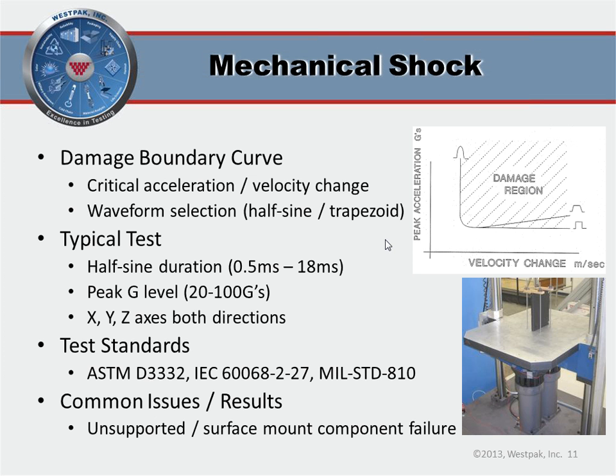For velocity change, however, you can actually subject the human head to hundreds of Gs without damage as long as the duration of that input is fairly short, and therefore the velocity change, or the area under the acceleration versus time pulse, is short. Those of you who have fallen off a bicycle or hit your head on the pavement, things like that, I guarantee you're going to generate more than 15 Gs. The chances are pretty good that you'll survive that unless the duration of the pulse is very long, and you've got a problem. So in mechanical shock testing, we're looking for both of those characteristics.